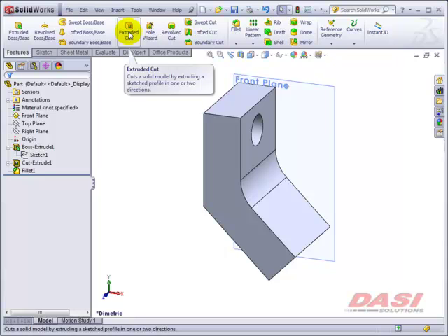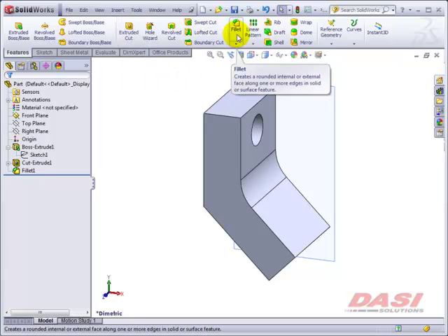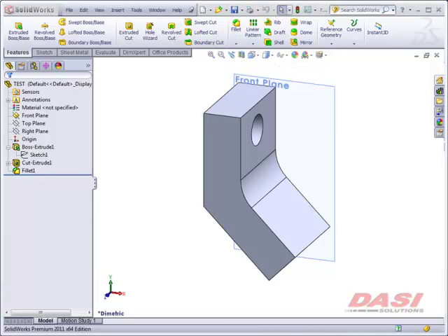But not all features are sketch-based features. We also have tools like fillet, which do not require sketch geometry. We call these applied features. That means that there are two basic types of features: sketch-based features and applied features. In order to construct our part, we will need to use a combination of sketches, sketch-based features, and applied features all together. In a nutshell, we may break the modeling process down to 3 steps.